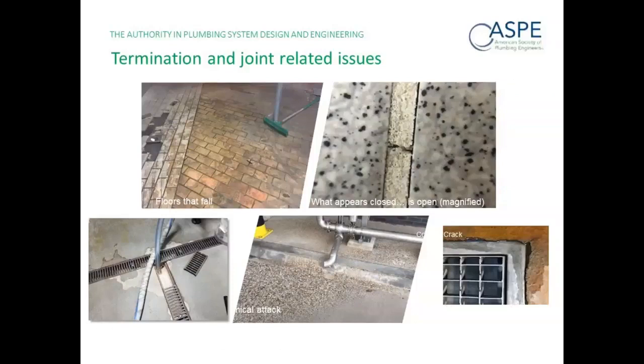So if you do have joints or joint material anywhere it's starting and stopping, it's not only important to have hydrophobic materials, but hydrophobic materials that are able to expand and contract at the same rate of thermal expansion as dissimilar materials are. So here's just a bunch of different images of the ways essentially not to do it, using T's or joints, and you can see quickly how the difference in thermal expansion can delaminate a floor system. It doesn't take very long to do it.